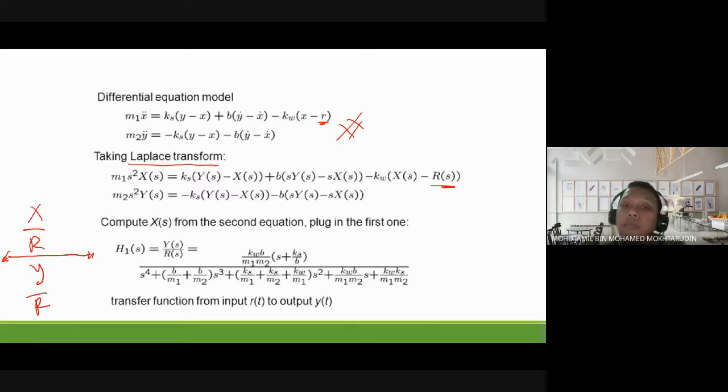So you can write in terms of matrix and use Cramer's rule. Or in this example, dia guna substitution. Okay. So substitution, it looks macam mana ni tiba-tiba dapat. Okay. So I think it's better if you use Cramer's rule. Because later on there will be more than 2 degree of freedom system, maybe 3 degree of freedom. So using substitution memang susah, okay? Memang difficult lah. So you need to use by matrix or Cramer's rule, which is simpler.